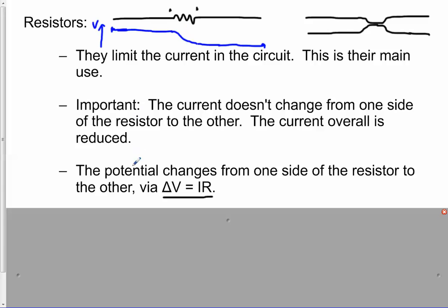Okay, so that's what I want you to think of in terms of delta V. And you can measure it. Delta V equals IR, so you have the R for the resistor times the current of the whole thing. Remember, that's what we said in point 2: there's one current for this whole wire from beginning to end. And so the delta V drops right where the resistance occurs.